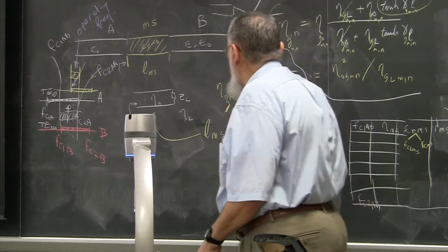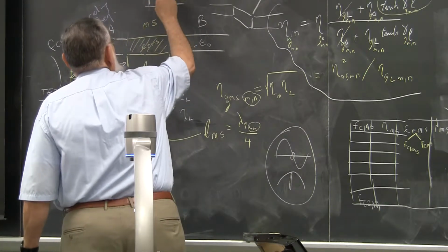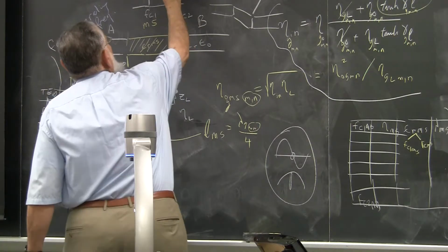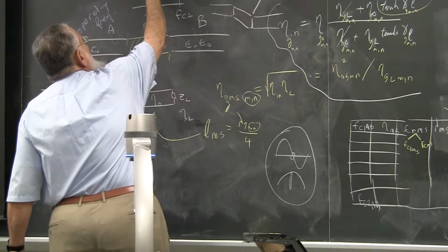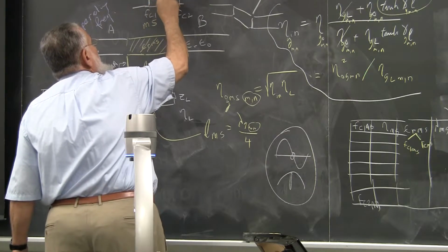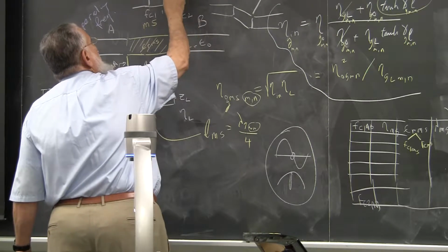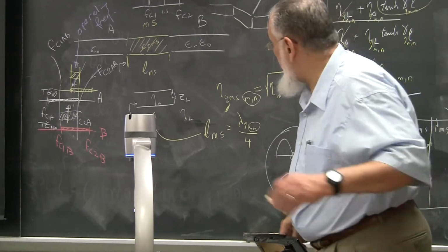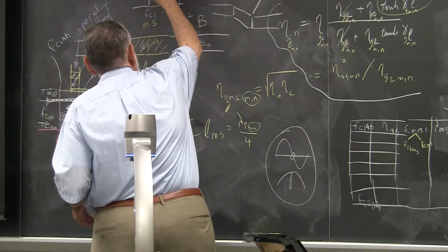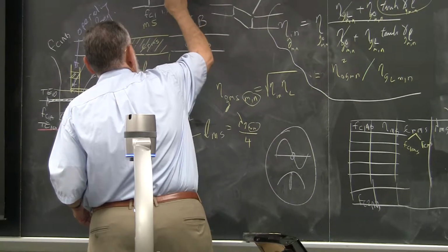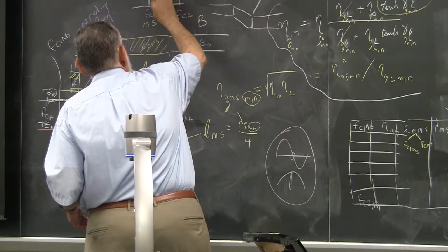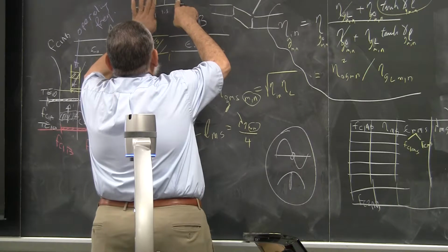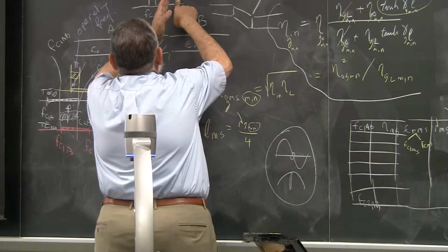Now, what I wanted to add is the attenuation. If you remember, if this is FC1 and FC2, the E10 mode, the attenuation almost goes to infinity here, dips around 1.5 and grows again. So as you can see, things are not exactly symmetrical in terms of the bandwidth, right? So usually if you want to do this kind of a situation with attenuation, with losses, right, you end up with some different margins on the sides. You have a bigger margin here. You don't want to come too close here if you want to maintain a decent attenuation.